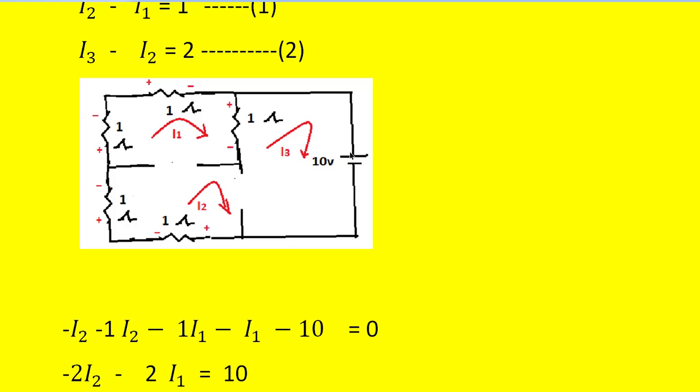So here we have the voltage source, and in the assumed current direction I3, first we are facing the plus sign here, next the negative terminal. So getting plus first, next negative means it will be treated as voltage drop, and voltage drop will get the negative sign. So we put here minus 10 is equal to 0. So we have written the loop equation for this super mesh circuit.